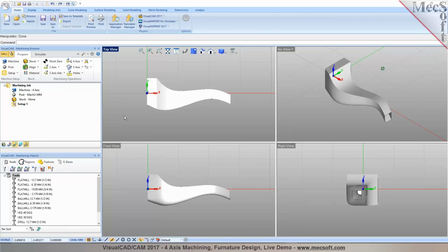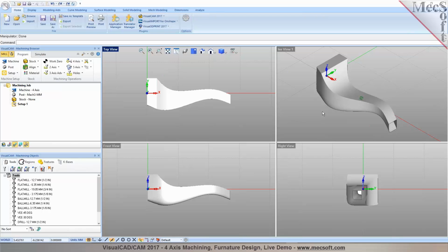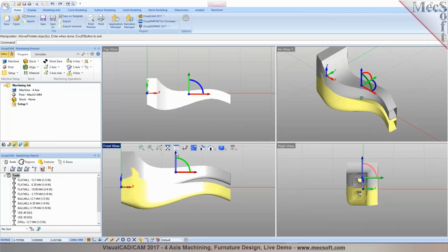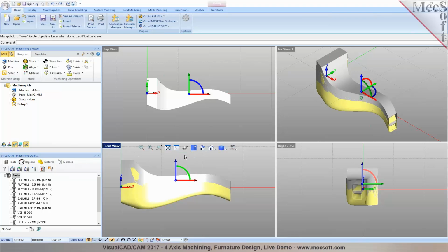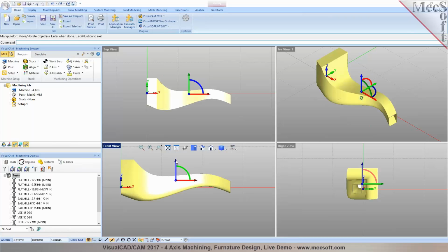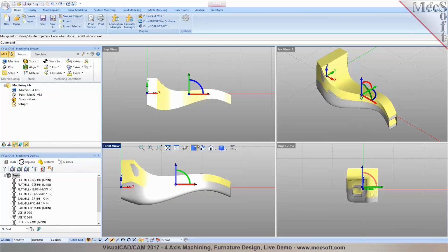Now, any questions so far? Can we move the parts so there are no parts below the 0 line? Yeah, meaning this section in here, you want to move it up slightly. I could say move it up by 2 millimeters. That was too high. I can go down maybe -1 millimeter. So now we moved it, but then you have a little portion that's sticking below the rotation center in here. So I'm going to go down by -0.5. So you can specify the distance you want to move it around.